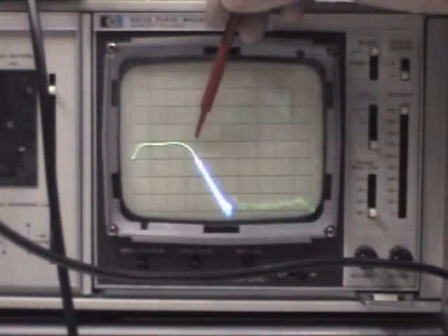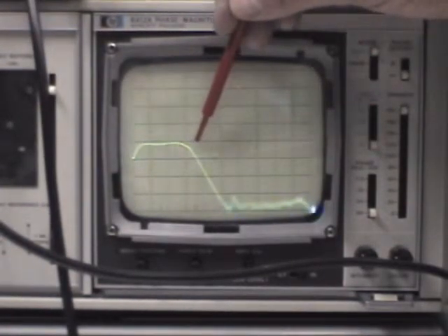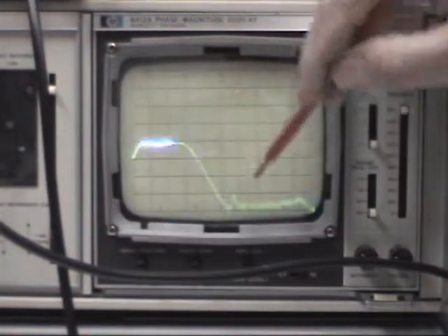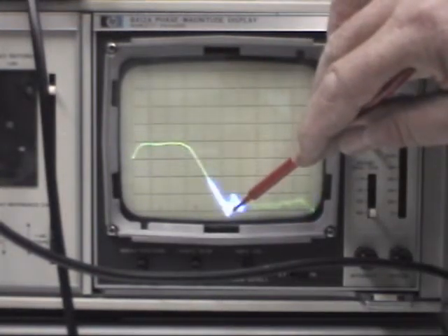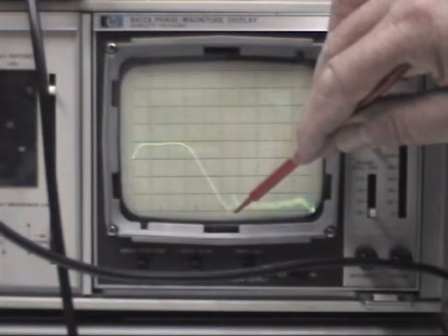So actually 111. So let's take a look at it a little closer to where we can get a little more detail. We'll switch from full sweep on the generator to video sweep, and now we're sweeping between 1 megahertz and 50 megahertz. So basically we have 5 megahertz per division here. We can look here, here's 5, 10, 15. So we start rolling off right a little over 15 megahertz. And down here, this is about 40 dB down.